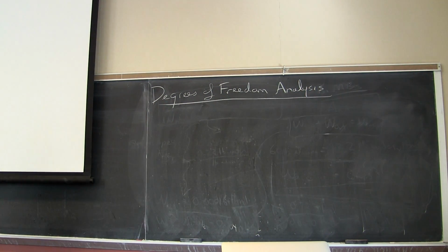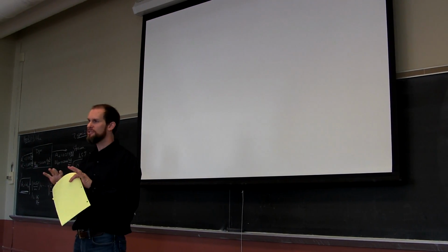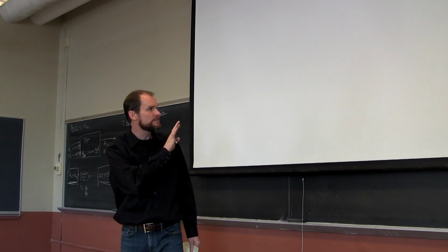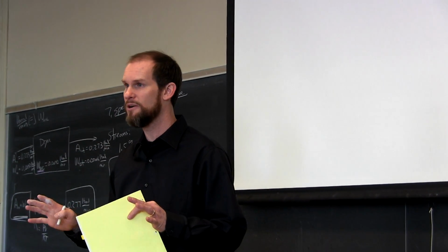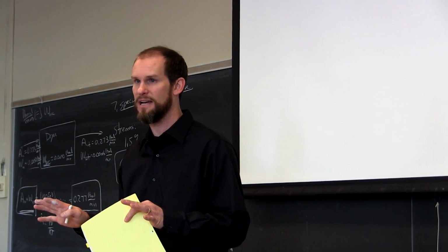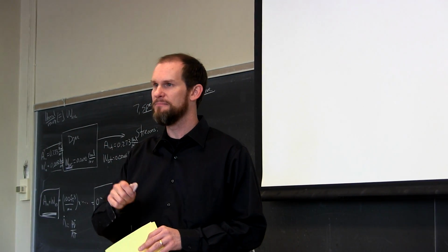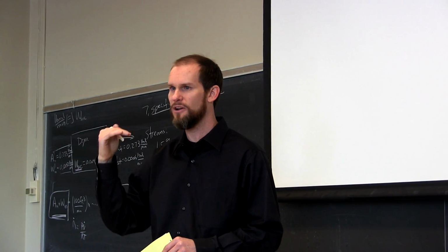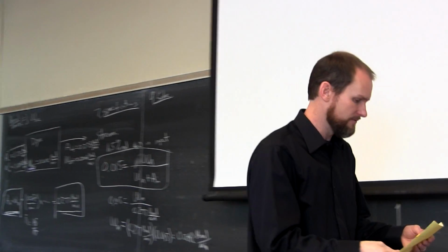All right, so there can be a lot of things to keep track of in these problems: flows in and out, specifications, etc. Sometimes it helps to just get a good idea of, do I understand the whole problem? To do that, we have a technique called degrees of freedom analysis, where we analyze, do I know enough about the problem? Do we have everything set? This is a tool to help make it easier, and it helps us count all of the equations and all the things going on in the system. So we want to learn how to do that carefully.